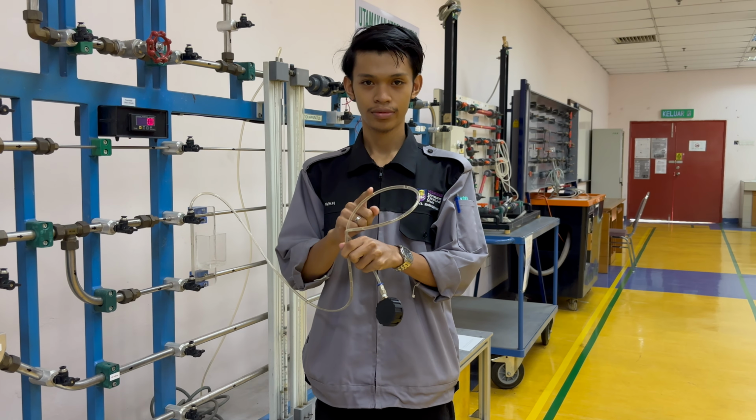The flow rate was then adjusted to different values and the upstream and downstream pressure readings were recorded again for the same pipe. After completing all readings for one pipe, the pressure gauge tubes were carefully detached and connected to the upstream and downstream tapping points of the next pipe sample. The same procedure was then repeated for the new pipe.